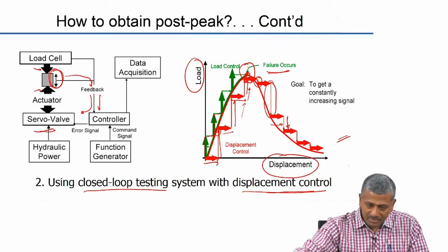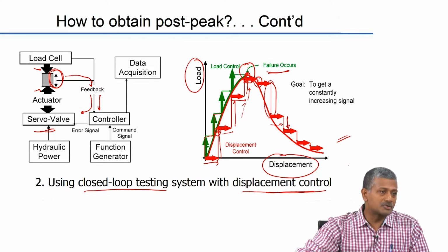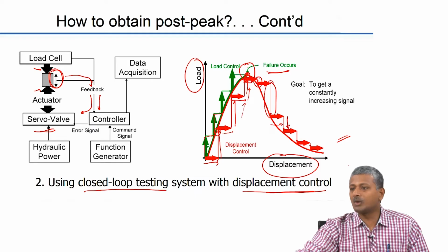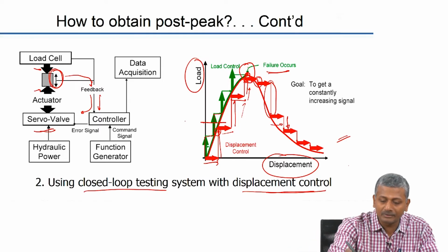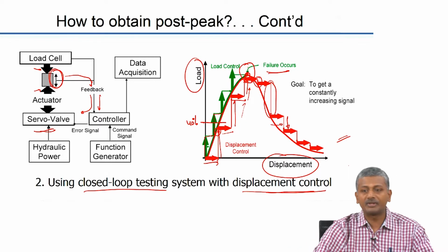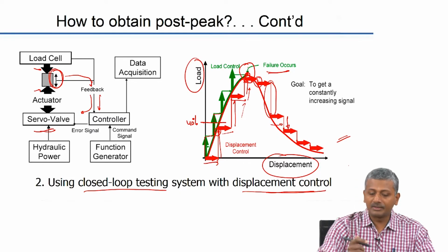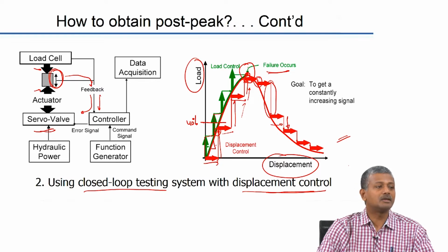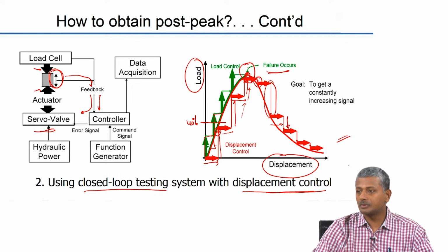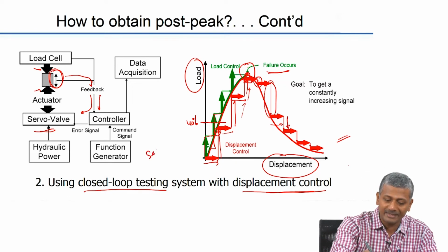One thing which we have not discussed here is how do you determine the elastic modulus of the concrete. There are different ways of determining the elastic modulus, because the stress strain curve is mostly non-linear. You do not get one single value of the elastic modulus. What you do is then rely on certain values, assuming that there is a significant amount of linearity in the system, and generally we assume that linearity exists only up to about 40% of the ultimate load. So, if you take a slope up to about 40% of the ultimate load, then you get a value which is close to your elastic modulus, and that is usually called a secant modulus.